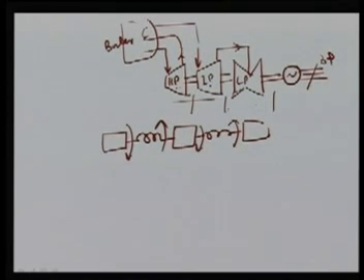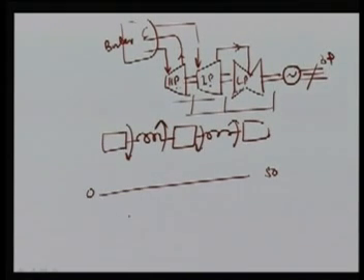So, if your system operates from 0 hertz to 50 hertz, and we analyze the complete system dynamics including the turbines as well, then you will find some frequency in the range of 2 hertz, and the remaining you will find at intermediate values less than 50 hertz. These frequencies of oscillations are the torsional modes of oscillation.